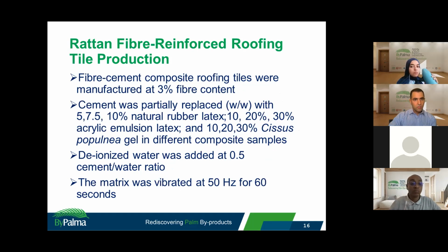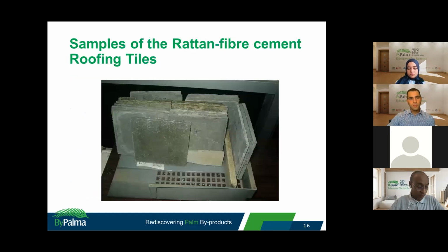These ratios were based on preliminary studies that we have conducted in this area. We have actually previously published some studies here, and those ratios were based on our preliminary findings. We used deionized water for the production at a 0.5 water-cement ratio. We also vibrated the products at 50 Hertz for 60 seconds, also based on preliminary studies. And these are samples of the boards that were produced.